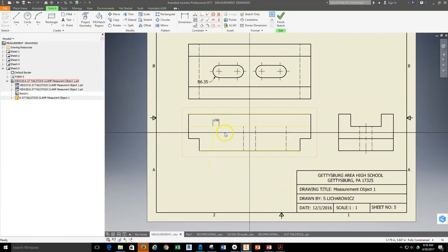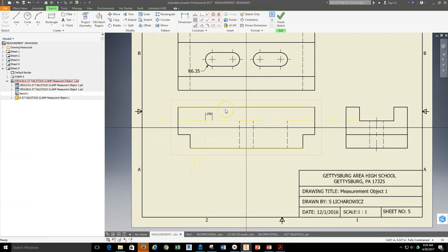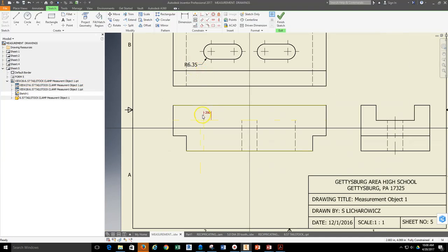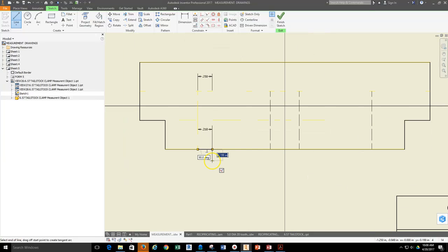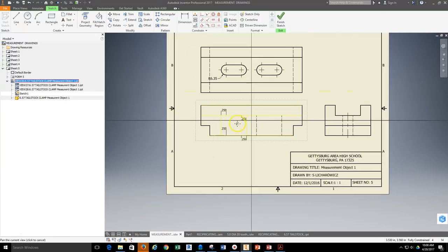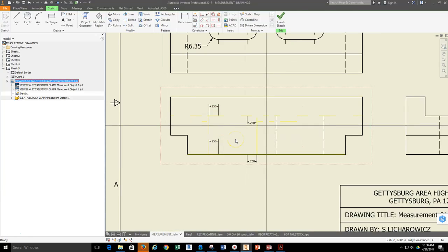Because this is an inch drawing and not a metric drawing, we're only dimensioning it in metric, the distance over will be 0.25. That's the conversion for millimeters to inches. We'll do the exact same thing down here at the bottom and draw over 0.25 as well, because we want the endpoints of those two lines at that point for us to utilize. Okay? And then we'll keep doing that for every one of these lines that we need to create. So 0.25, and then we'll do it again here. Come over 0.25. Okay? And once we have this set up, I'll show you the finishing process to get the center lines or center marks in.